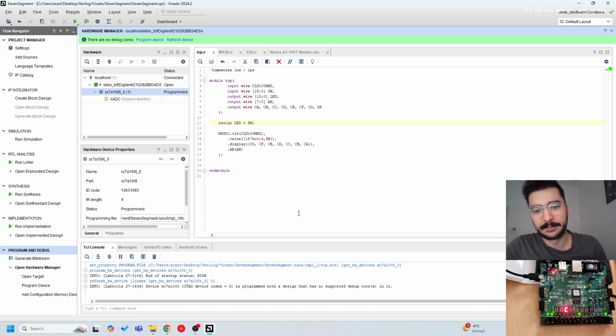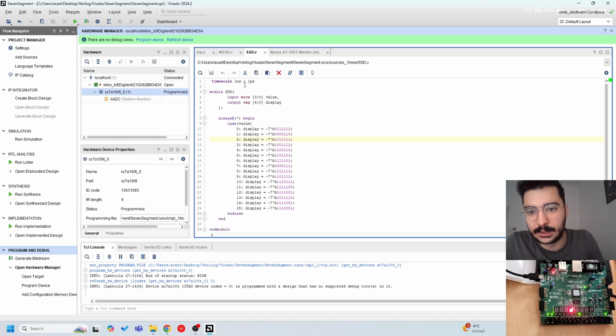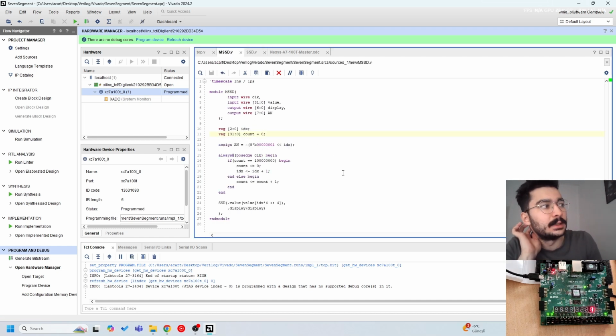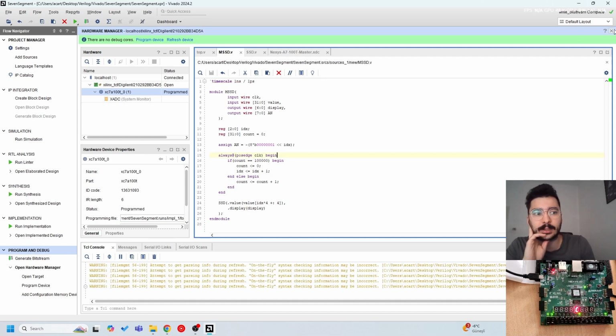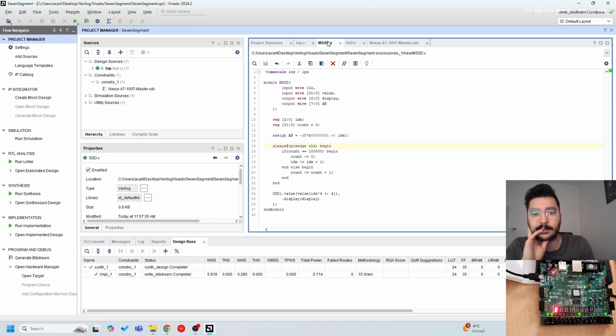but now this is too slow. Now we need to find a sweet spot, and it's a wide range, but usually the eye cannot see flicker if you exceed 100 Hertz. So what I usually do is I set it at 1 kilohertz, which is not too high, but it's not noticeable. It seems to work. So let's try it with 1 kilohertz now.